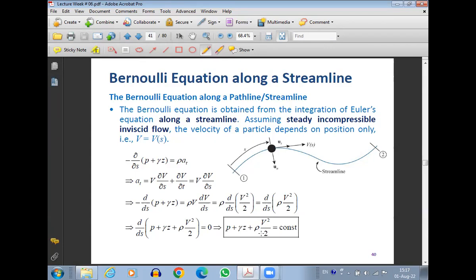So you have a fluid flow, fluid is moving from one point to another point, and Bernoulli equation can be applied at any point within the fluid flow if it is along the streamline. So this is the first condition. The second condition is about the fluid itself. The fluid should be incompressible. Incompressible means mostly liquids, because the gases are considered compressible. So this Bernoulli equation cannot be applied directly over the gases.